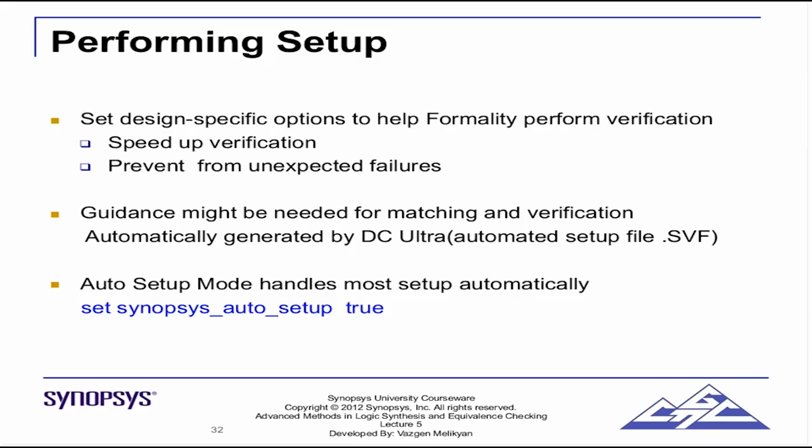For example, clock gating. Now clock gating, the step in synthesis, will add a latch and an AND gate or an integrated clock gating cell. Now this integrated clock gating cell is extra, right? In RTL, the enable pin gating is on the data pin, not on the clock. But in the netlist, as a result of clock gating, the gating part shifts to the clock from the data pin. So now the compare points are not equivalent. If you compare the clock connection or the data connection for this clock, they are not equivalent from RTL to netlist because of the clock gating.